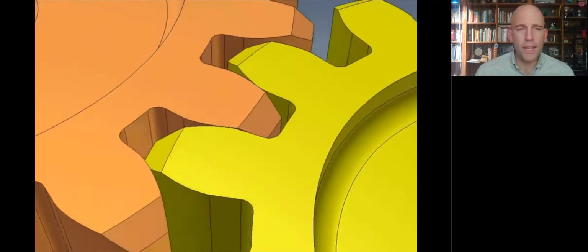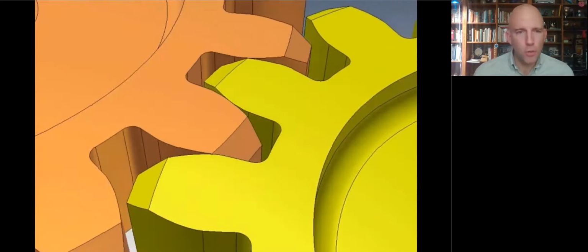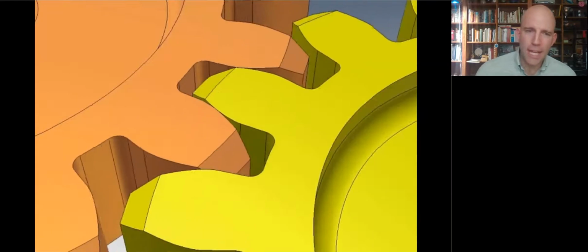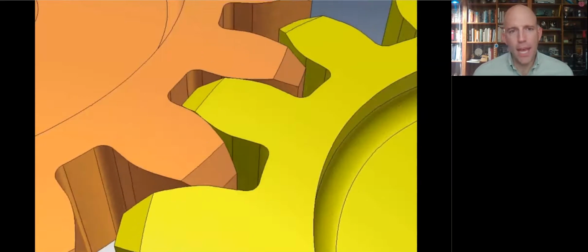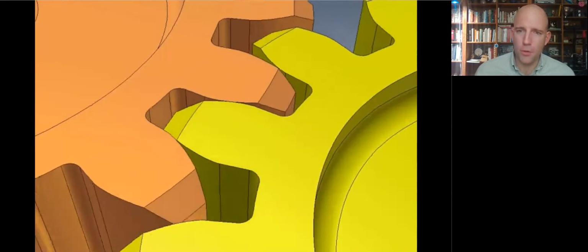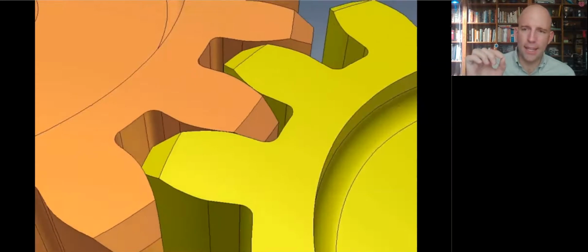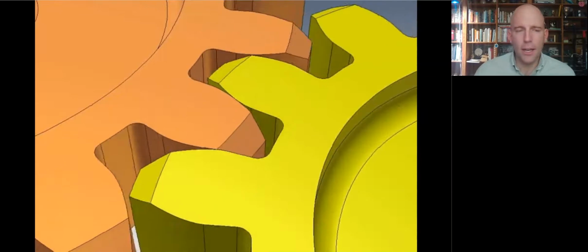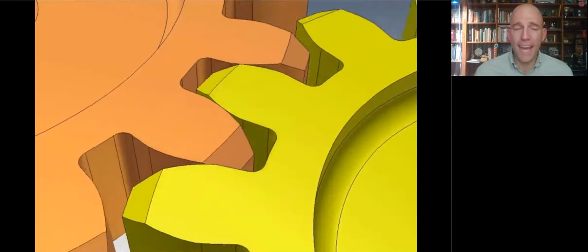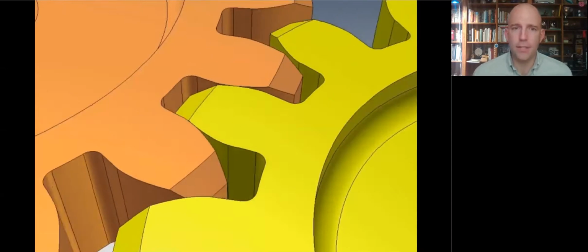All right, now let's take a closer look at these teeth. And when they're moving, you can see that they're going to mesh and then unmesh. And if you look very closely, you'll notice that they're sliding during most of the mesh. If you pick a point on one of these gear teeth, you'll see that it's going to slide in and then slide out of contact with the other gear. They can't roll. That's not possible given the geometry. They have to slide some.